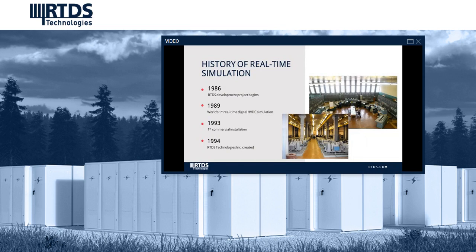Before the emergence of real-time simulation, the main way of testing HVDC controls in the laboratory prior to deployment was by using analog simulators. These were essentially scaled-down physical models of the network of interest that could then be connected to the control cubicles for the HVDC project to test their dynamic performance, for example, and to ensure they were functioning as expected through a wide range of conditions.